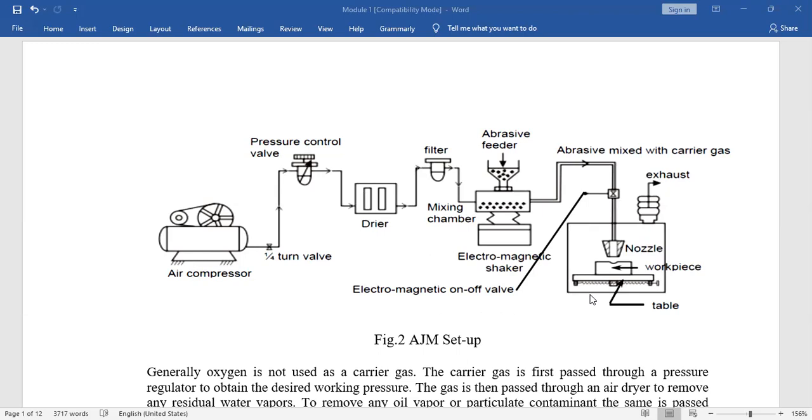One disadvantage of the abrasive particle is that it cannot be used again and again. It can be used only once or twice. Why? Because when it is used here, the sharp edges are broken into small particles. When the sharp edges are broken, it is not responsible for the cutting action in the next step. That is why the abrasive particle cannot be reused again and again.